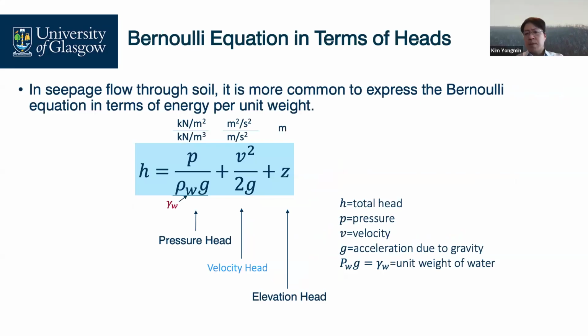This water flow is governed by the principle of the Bernoulli equation, which is expressed by a head, like a pressure head, velocity head, elevation head. The term head is used because the term h in the Bernoulli equation has the unit of length: meter, centimeter, millimeter.